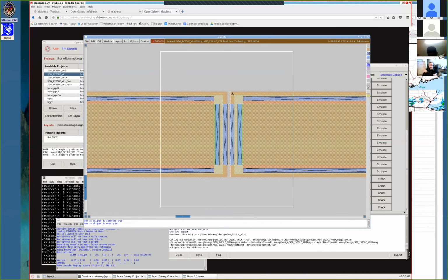The reason that every single device is surrounded by a guard ring is largely so that we do not have to take care of all the design rules, so we're not exposing the design rules on the poly and diffusion layers. Because pretty much if you don't match up the guard rings of cells, then you're going to violate the design rules for the guard rings, and that's sufficient to make sure that the entire cell is DRC clean. If I take, for instance, this cell